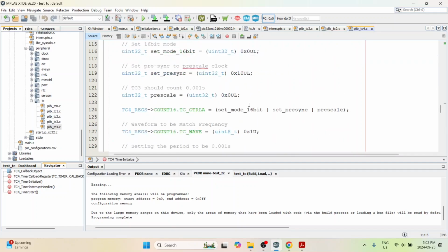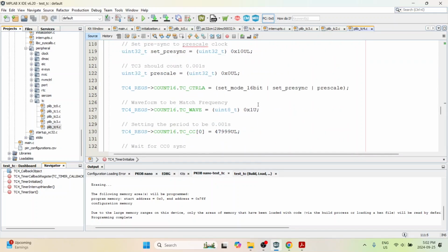And as I said, the reason why this is so important is because in power electronics, you may have to establish separate control loops which are totally independent from your pulse width modulation. Most of us power electronics people are interested in controlling the converter, and most of us will use PWM in order to execute a control loop once every PWM cycle. But there are certain other control loops which may be totally independent, things like temperature control, pressure control, maybe even voltage control or frequency control, things which are much slower, and for which you cannot use fast controls such as the ones implemented with our pulse width modulation. For that reason, you can use timer counters to set totally different time intervals with which you can implement your control algorithms.